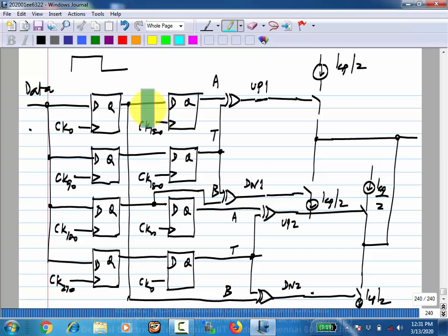And at some point it starts becoming super linear. Okay. And at some point you can't make it at all, because you try to increase the size of the devices to increase the GM, but then the self-capacitance loading increases in the same proportion and the speed doesn't increase at all. Okay, this is what you would see, and you would have seen in some simple examples we have considered in assignments and so on, right? So it doesn't work at all.